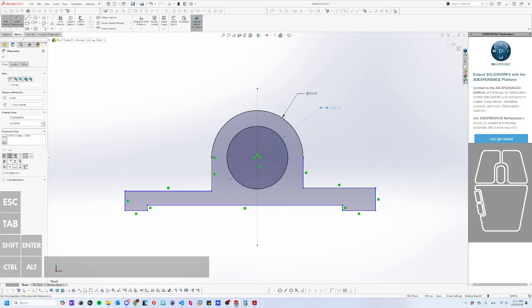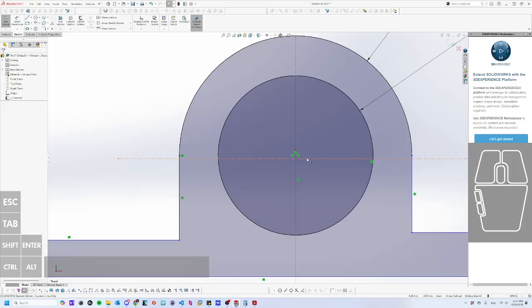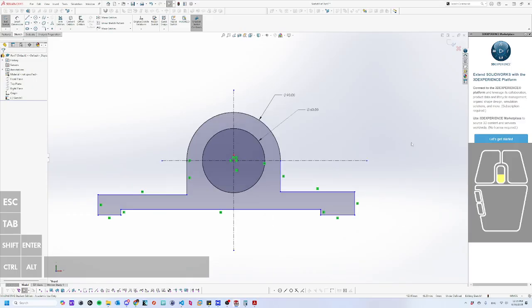Let's put in this horizontal center line so that we can add the dimension related to that. Whoops. I'm just going to draw a horizontal line. I missed the origin, so this time I'm going to click on it, control click on the origin, hit coincident, and now it's lined up. It looks like this one didn't line up either, so I'm skipping ahead. I'll do that later, actually.